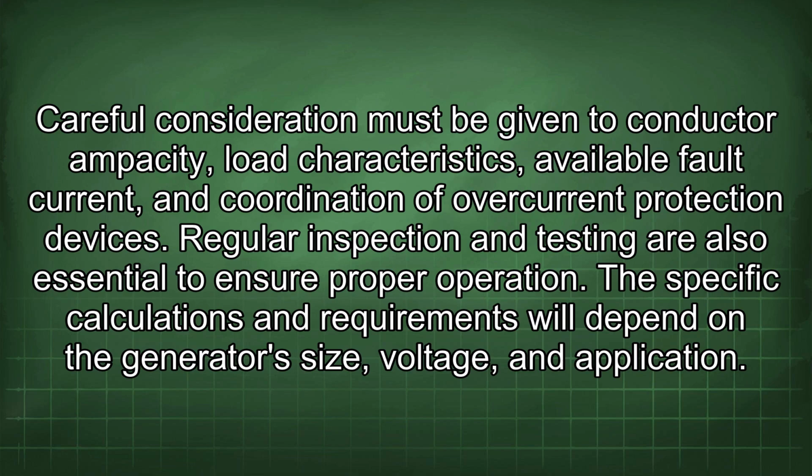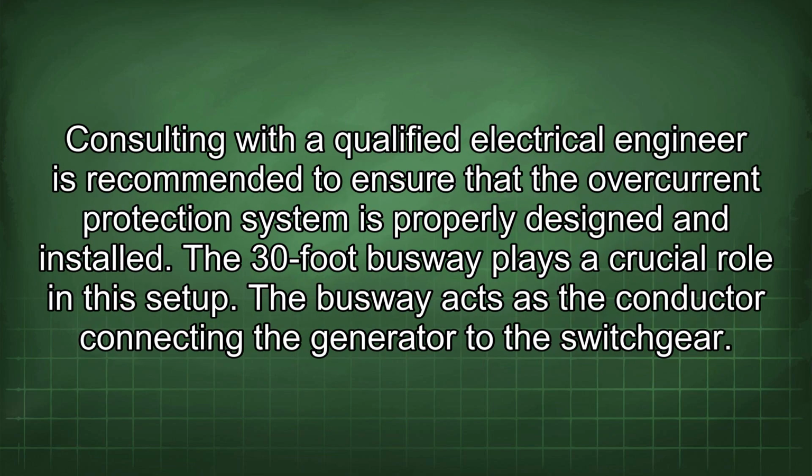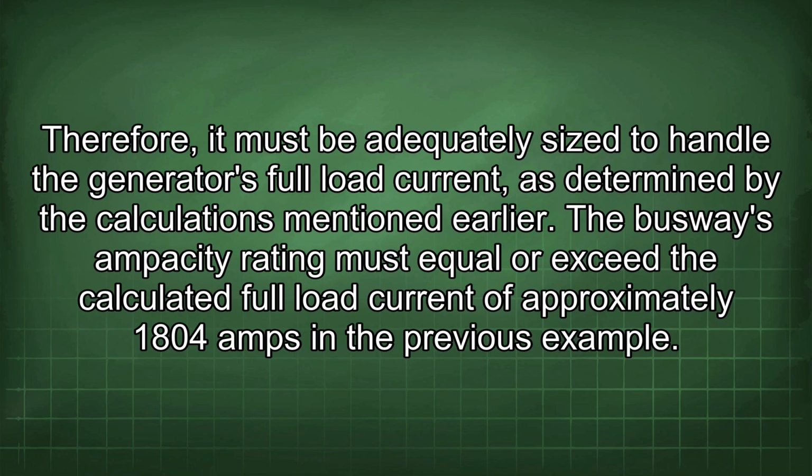The specific calculations and requirements will depend on the generator's size, voltage, and application. Consulting with a qualified electrical engineer is recommended to ensure that the overcurrent protection system is properly designed and installed. The 30-foot busway plays a crucial role in this setup. The busway acts as the conductor connecting the generator to the switchgear. Therefore, it must be adequately sized to handle the generator's full load current, as determined by the calculations mentioned earlier.